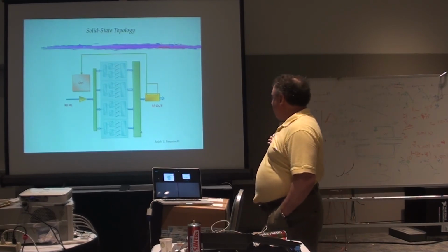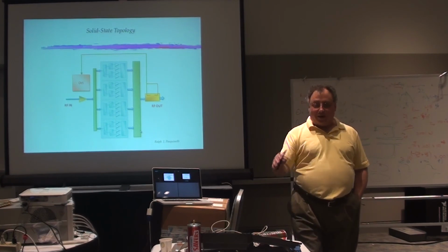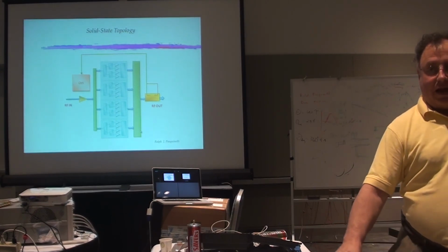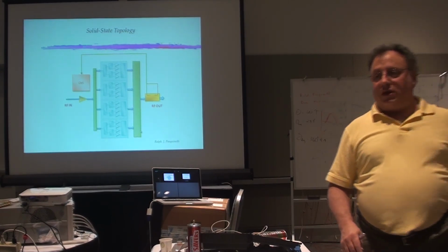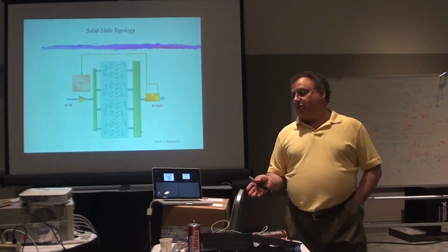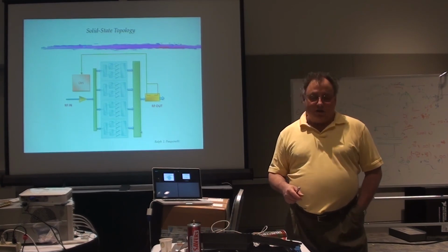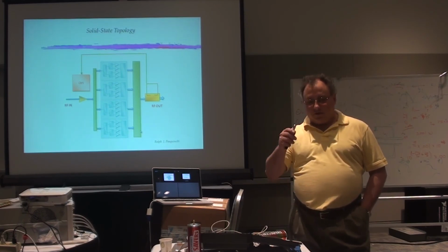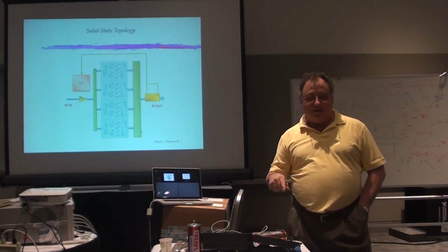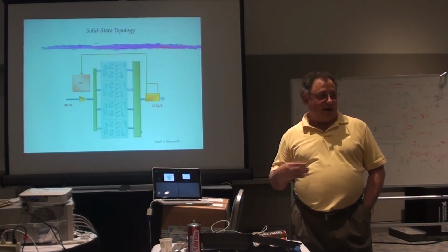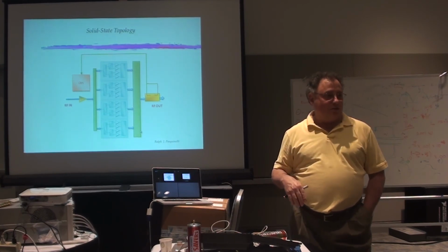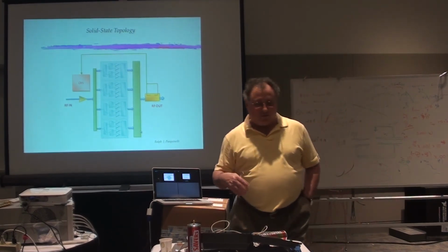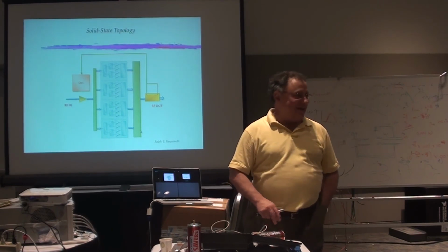And solid state's coming along, but if we're working in the microwave regime, right now at LCLS-II, which is the light source they're building at SLAC, in the old SLAC tunnel, they're going to use solid state CW amplifiers at 1.3 gigahertz. And at 1.3 gigahertz, those will end up costing probably $15 to $20 a watt, so it's a very expensive thing to do. A colleague of mine and myself at Fermilab just patented running a magnetron in the injection lock mode, and that is a $2 to $3 a watt solution, which we have already proven running a superconducting cavity at 2.45, and we're looking to do the next system at 1.3 gigahertz if someone will give us some money. So we're still waiting for that.